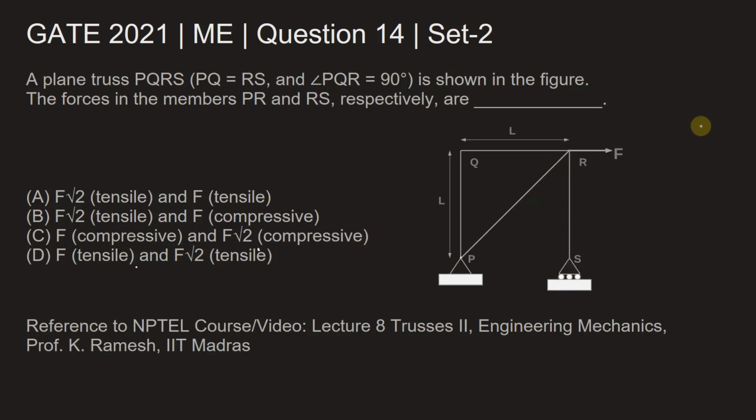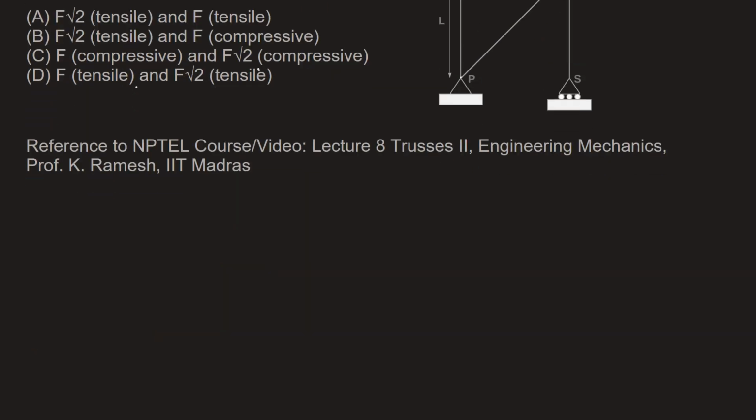As we know, we will start with finding out the external reactions at these supports. Now this can be done using two equilibrium equations. It is either summation FH equal to 0, which says that the sum of all external horizontal forces in the truss is 0, or summation of moment at point P, or around any point, is 0; we can use point P conveniently.